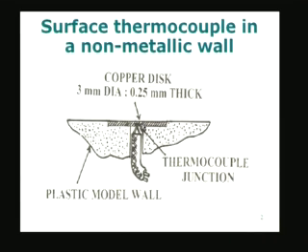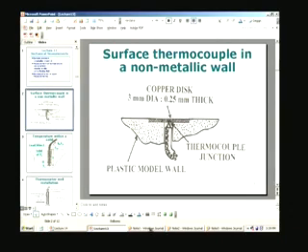T t. Okay. So, I will then equate this to the heat loss through the thermocouple wire, and I will get an expression between the temperature of the fluid T f, the temperature of the junction which is now indicated by the measurement, and the ambient temperature T infinity. Therefore, if two of them are known, the third one can be determined. So, let us just look at this situation by going back to the board.